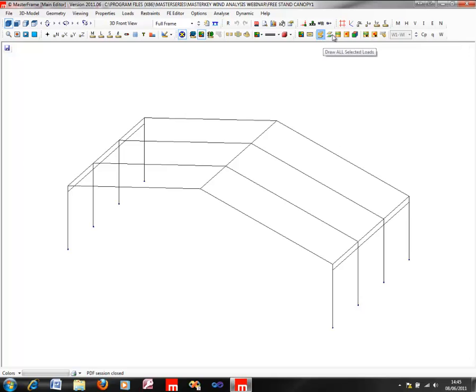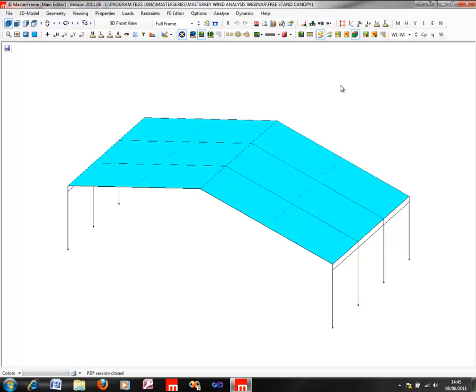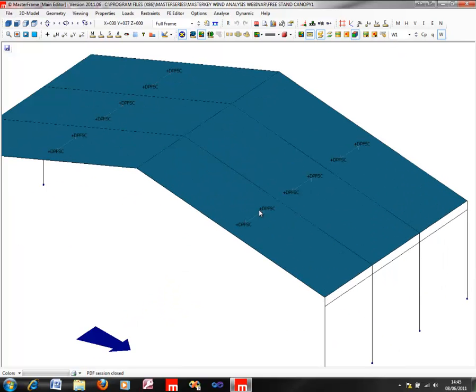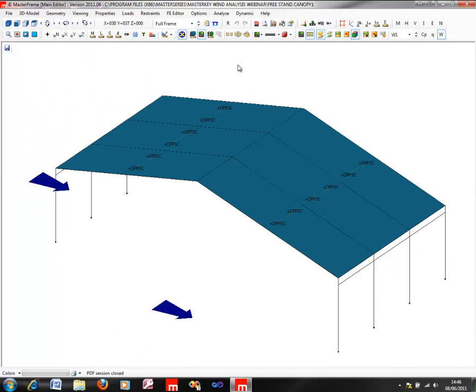For our freestanding canopy, we quite simply have two surfaces here, and basically it's going to look at a surface, not see any wall connected to it whatsoever, and therefore decide that it is a freestanding canopy. And again, if we put on our zoning designations for a particular wind direction, we have something called a dual-pitched freestanding canopy, DPFSC, as the zoning designation there. So again, there's an appropriate table in the code for that type of surface.